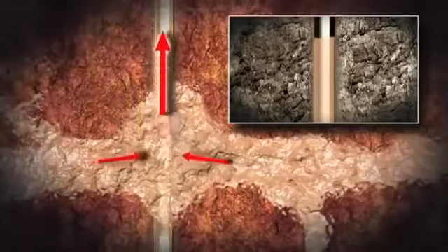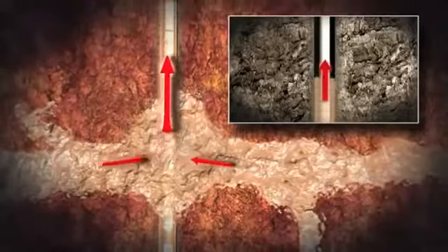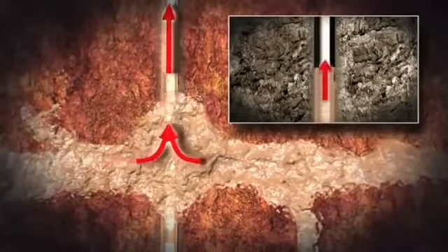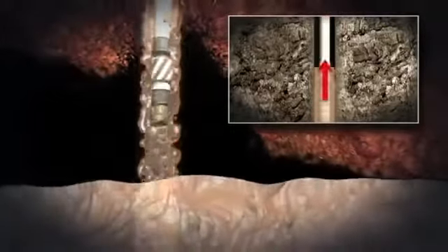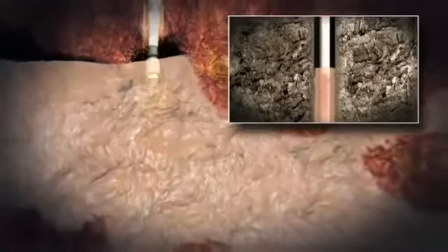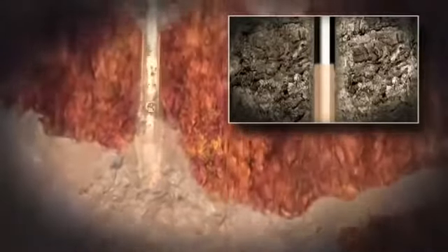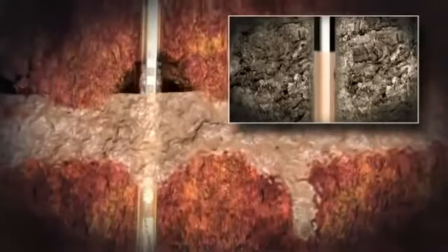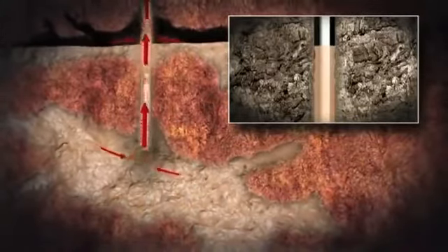Again, mud weight exceeds formation pressure and fluid losses begin. The loss of fluid reduces the hydrostatic pressure, and when it is lower than the formation pressure, gas enters the wellbore and causes a kick. Lost circulation material is added in an effort to seal the lower fractures, which allows the mud weight to be increased in an effort to control the kick from the upper fracture zone, resulting in a new round of fluid loss in the upper zone. This cycle defines a typical kick loss scenario that creates many problems.